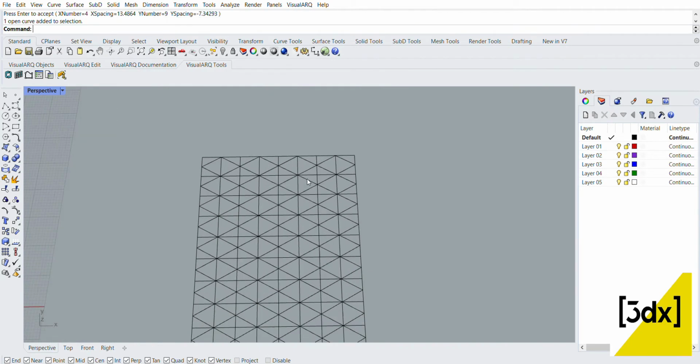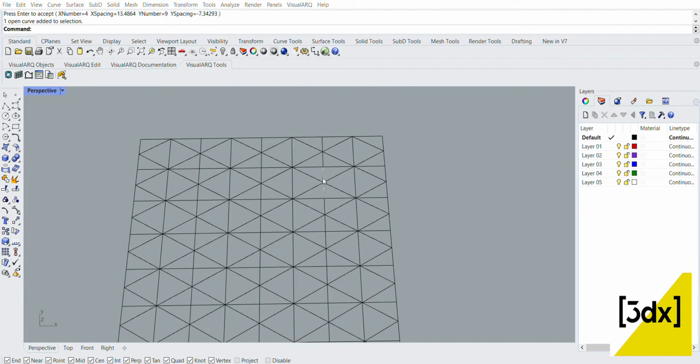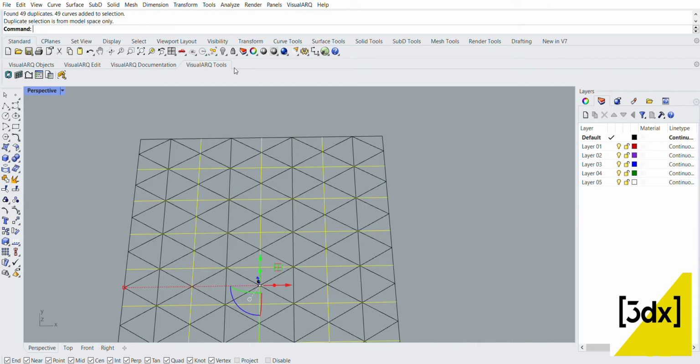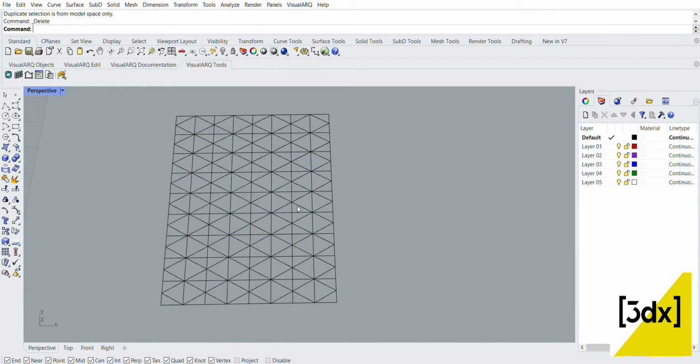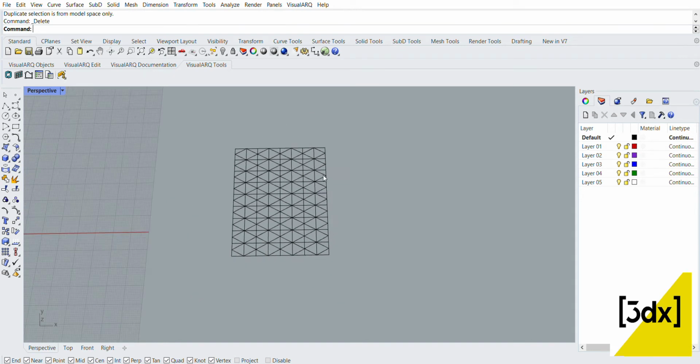So the thing is we have many overlay lines, so we should delete them by selecting. Go to the standard, go to select, and there will be select exact duplicate object. So these are the duplicate objects. I'm just selecting because we can't find them by clicking one by one, so these options come in handy.